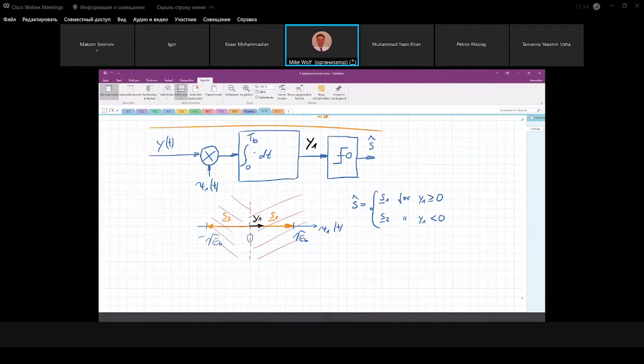You basically reduce the noise as much as possible, because we have this additive white Gaussian noise, and you reduce the noise variance as much as possible while keeping the desired signal as much as possible. So at the end, we maximize the so-called signal-to-noise ratio at the sampling times. This is what we are doing with this detector. So this matched filter approach provides insights into this problem.